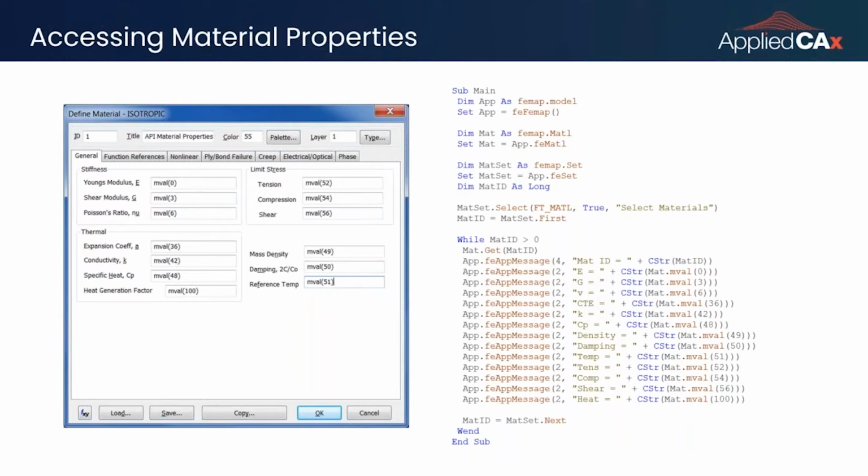Now, this isn't a terribly useful program in terms of gathering that information, but I'd say it's really useful in understanding how these programs work, because what I've labeled in each of the fields here corresponds to extracting that information using the API. So it's really a visual guide. If you wanted to modify material properties for a bunch of different composite materials, well, there are now some built-in tools in FEMAP that might be making some of my macros obsolete, but you could have a spreadsheet.